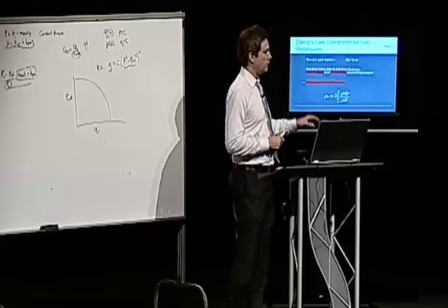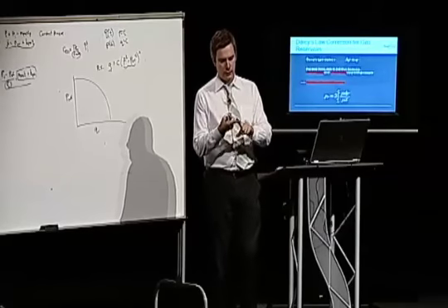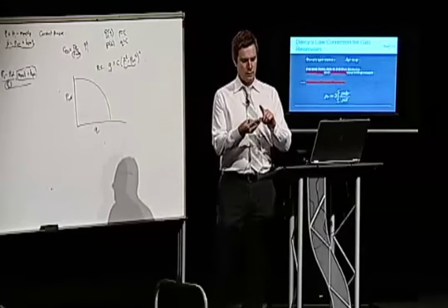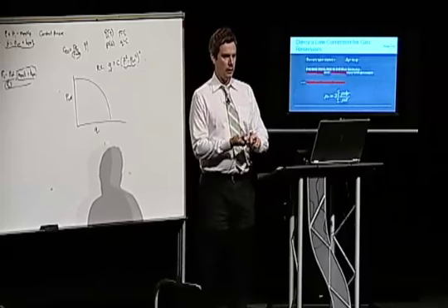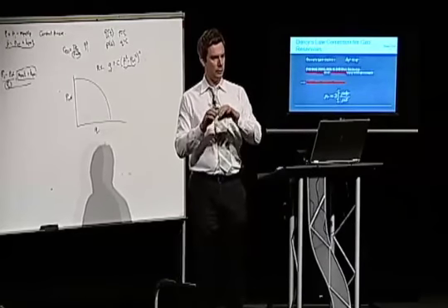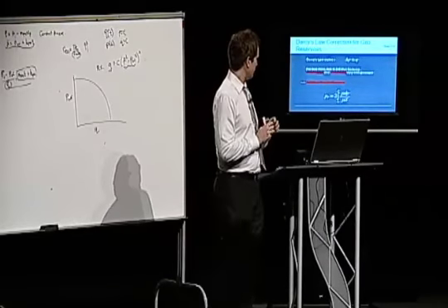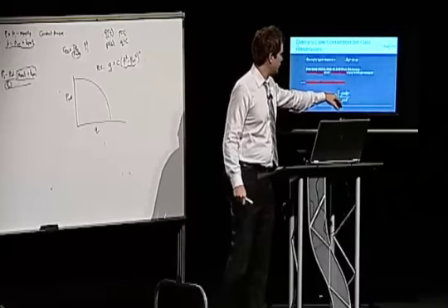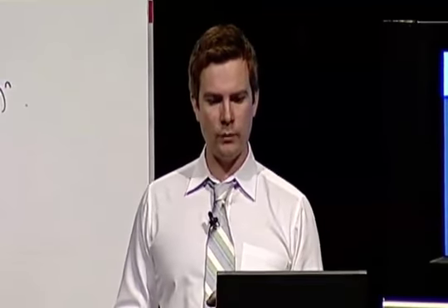So effectively what we do is, if you provide the gas composition, pressure and temperature, I can look up in a table or use an equation of state to determine a pseudo pressure and deliver that back to you. Okay, so it's a direct transformation. As soon as you've provided the pressure and the gas composition, I can give you the pseudo pressure. So this is an easy one to do.